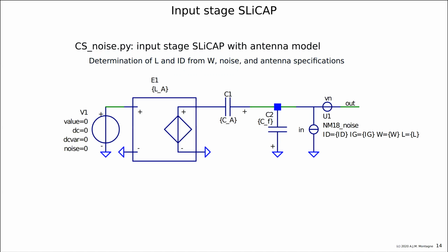So here is the circuit that we use. And now you see indeed that we have the noise sources of the MOSFET, but we have placed in parallel with the source CF, this feedback capacitance, because for the noise it is as if it is in parallel with the source. And maybe you see immediately what will happen if you shift Vn towards the direction of the electrical field, so towards the left.